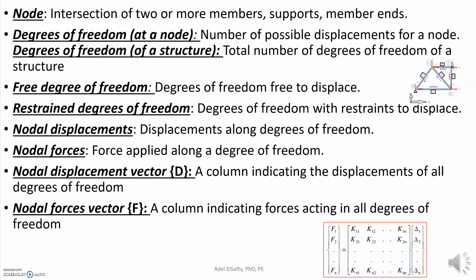All right, guys. So let's proceed with a new session on the trusses, and we are going to be talking about the member and node identification in the trusses. We find out that there are some terminologies that we need to be familiar with. The node, for instance. Each one of these intersections of two or more members is going to be called the node or the joint.